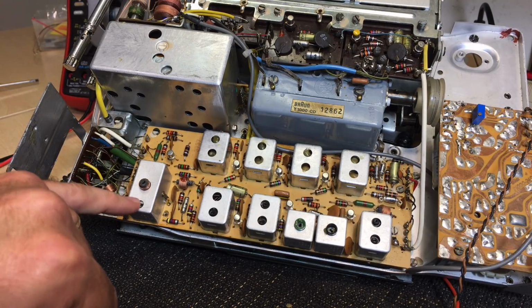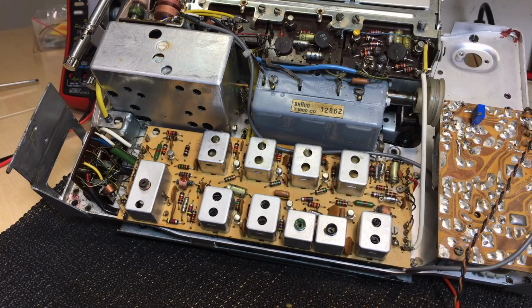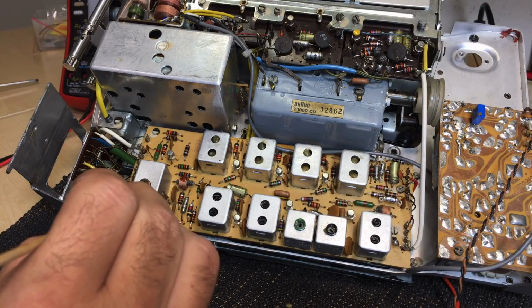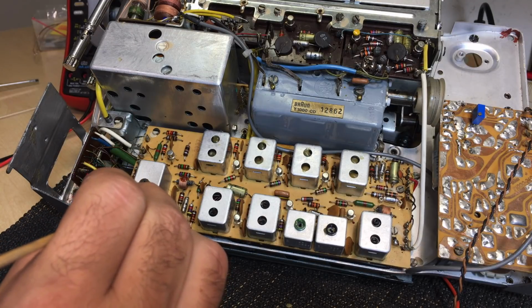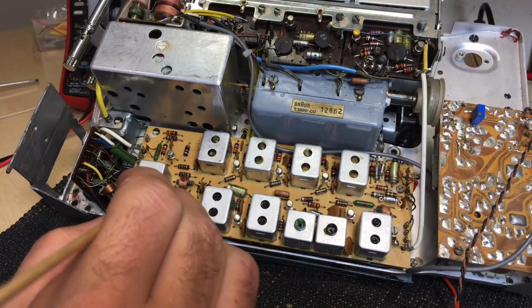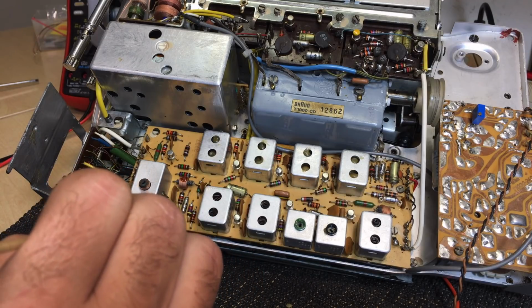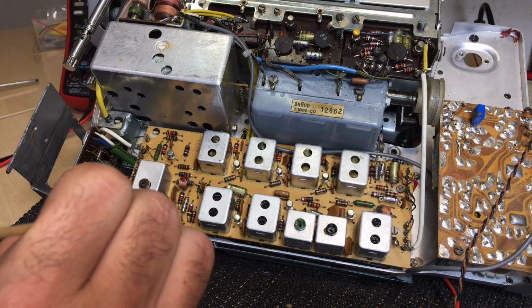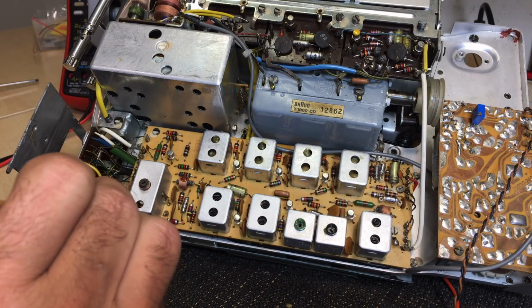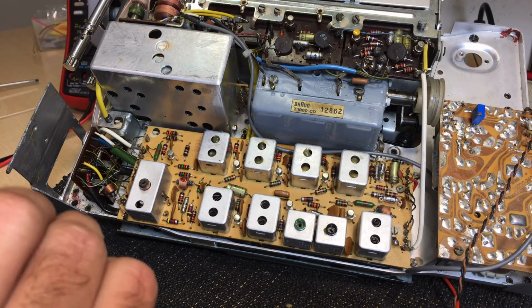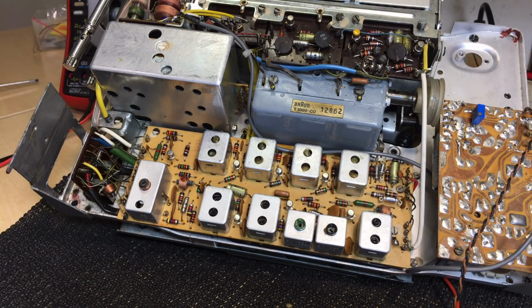If it's 2 kilohertz higher, say 457, you'll hear the same 2 kilohertz whistle. As you tune this closer and closer to 455, that difference becomes smaller. So that whistle drops in tone till it gets to the point where you don't hear it at all, which means it's less than 20 hertz difference. And when you go further the other way, you start hearing it because now the frequency difference is on the other side of the subtraction, if you know what I mean.